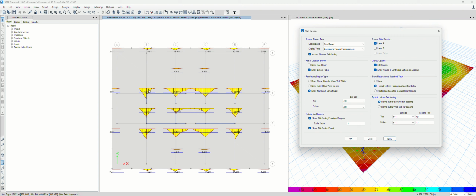But the bar you see on top of this is additional bar. Seems like we have a quite significant amount of additional bar we need to place at some middle of the mat, at the column, and then under the concrete wall, right? So because this is something being designed now, you need to really consider constructability as well as just engineering, how to organize this data so that construction is more reasonably doable, right?